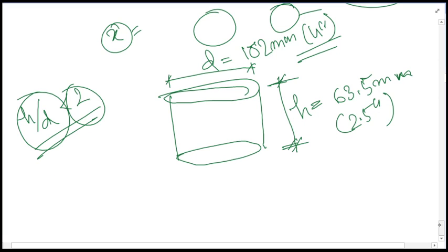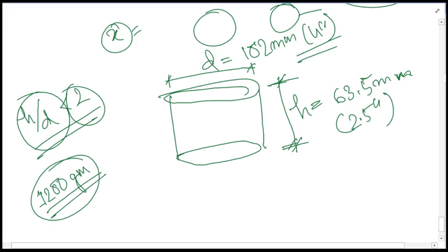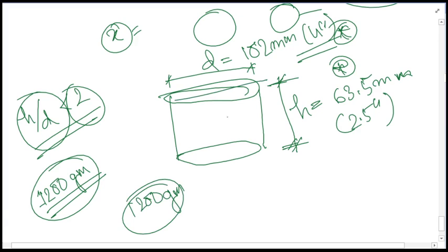and why we always target, just keep remembering one thing, that we always target for the total mixture equal to 1200 gram. This is our main target. Why? In practical sense, as these particular dimensions are fixed for this Marshall mix design, we always see that 1200 gram always fulfills this height, 63.5 height.